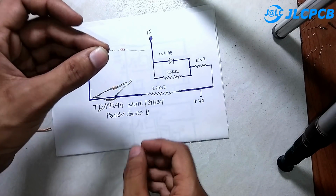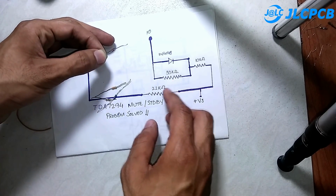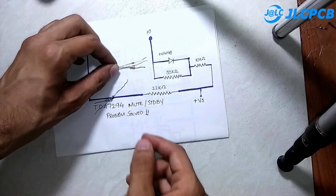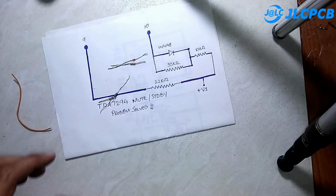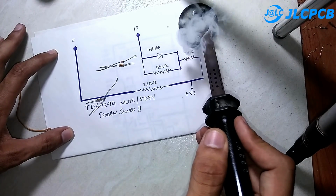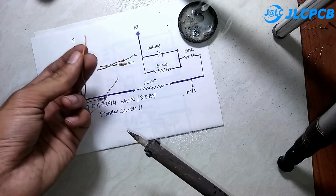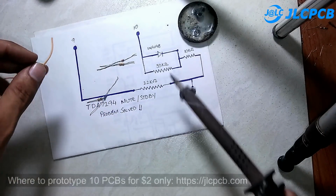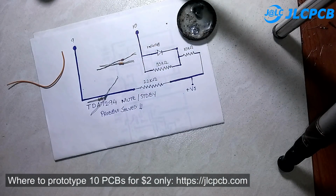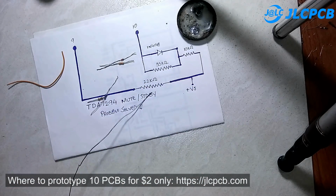So first of all I will pick up this 1N4148 diode, and I'll connect a 33 kilo ohm resistor in parallel with this diode. It's very simple to do. You just need these 4 components and a single small piece of wire. That's it. So I'll make the connections as they are in this circuit diagram.